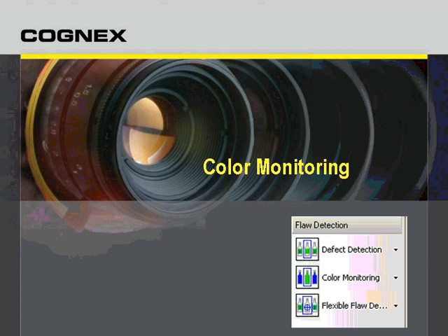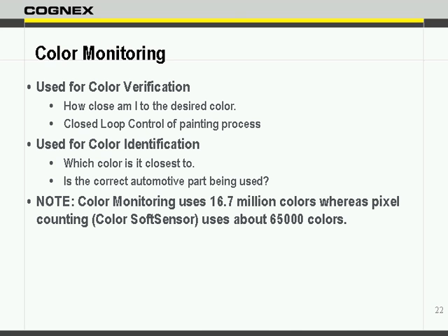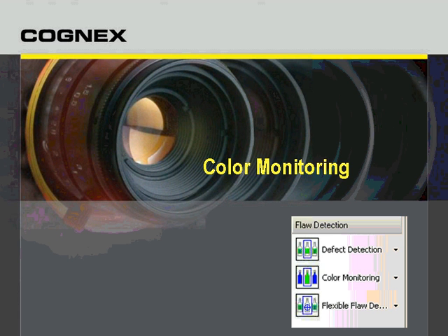This is a way to extract information based on color and do some thresholding and create new images based on that color information. And it's a way to pass that color information along to other tools, so that it can be used for other purposes, as in this case we used it for counting blobs. So another color tool that we have, so we've looked at pixel counting. And pixel counting can be used again for presence absence application. We want to make sure that a certain number of pixels of a certain number of colors are present in our field of view, our image.